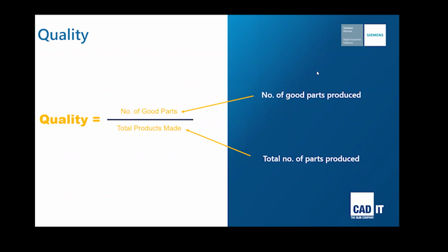And lastly, quality. This refers to the quality of parts and how often you make defects, and it's probably the biggest challenge. It's often the case that at the end of a production cycle, it's not known whether a good part or a bad part has been produced. Exceptions to this would be if the equipment has inbuilt inspection, such as on-machine probing, or perhaps the machine has crashed or experienced an issue and stopped early, which would be an obvious indication of a defective part.